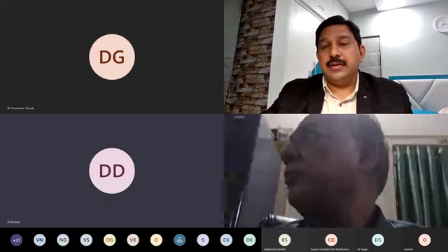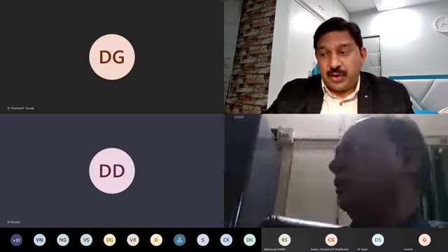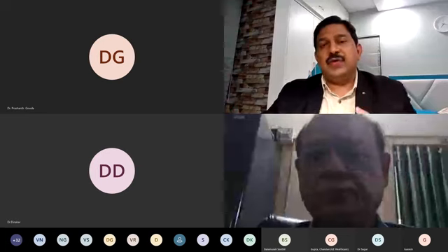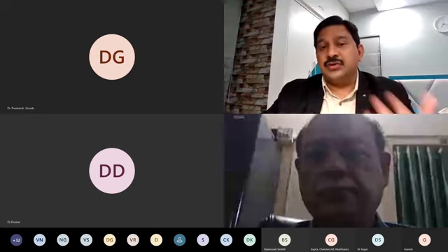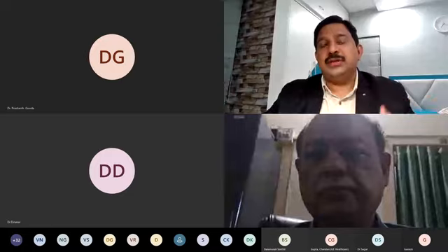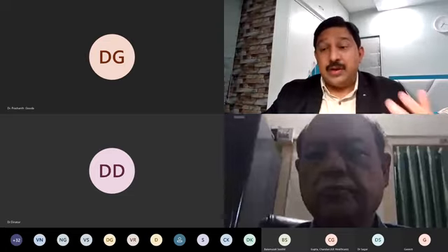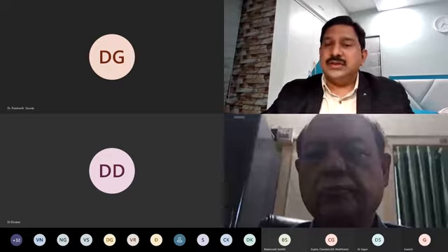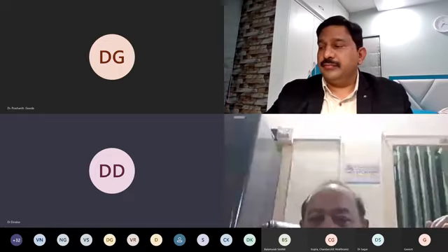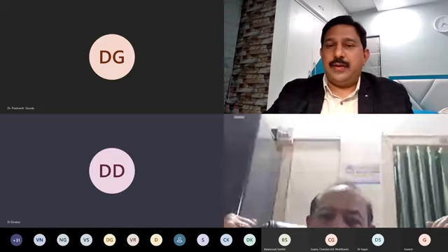Pathology equipment will take very little electricity, no? No, but if there are refrigerators in pathology and the blood bank, our machines and refrigerators are also on UPS. So we have to define what things are going to be on the UPS. If refrigerators are also there, or maybe a centrifuge also, then in that case the 60 kVA will not be enough. Okay, so probably then we have to go for dual, meaning 120 kVA.